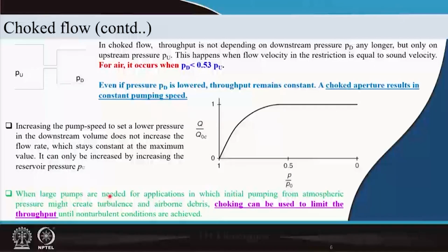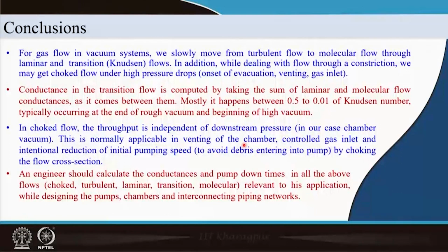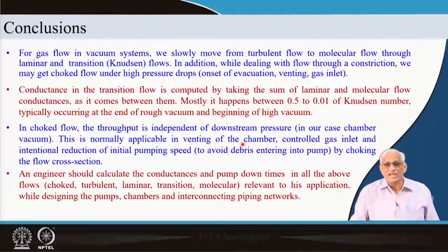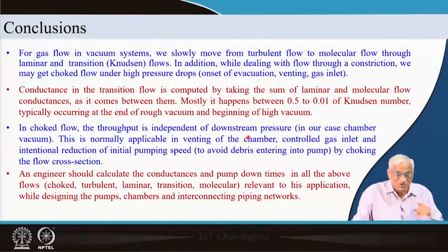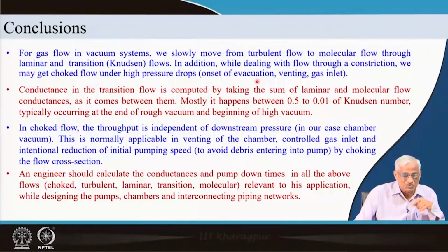So, you can avoid this by a slow and steady start. I just want you to be careful before you start operating pumps and designing the pipes. These two aspects, transition flow and choked flow, we have considered for your benefit, so that you are aware of these things. Sometimes it may not be needed, because it is a dry chamber, everything is dry, perfect condition, no problem, but situations will come where you have to understand transition flow and choked flow.